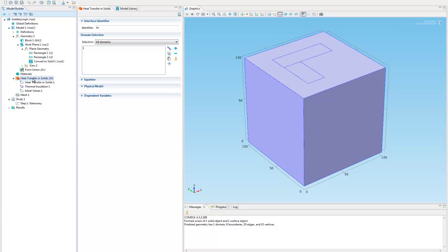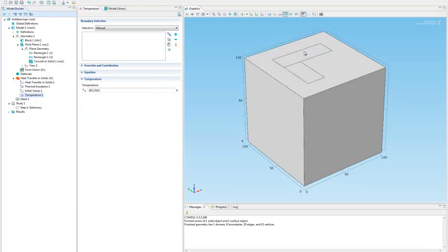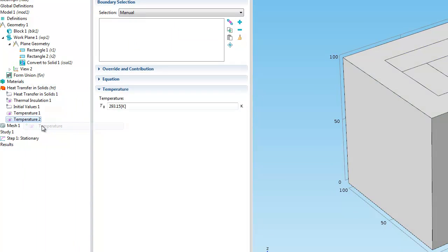So what should happen now if you want to apply boundary conditions? For example, I'm going to apply a temperature boundary condition on my model. These will remain as, or I should say, surfaces that I can apply boundary conditions to. So I've just put a boundary condition there. I believe in the problem that would be, for example, 20 degrees. And then if I did a different temperature for the rest of the material, I would do a separate temperature. So I can do the remainder of the surface and add that one in addition to these surfaces.